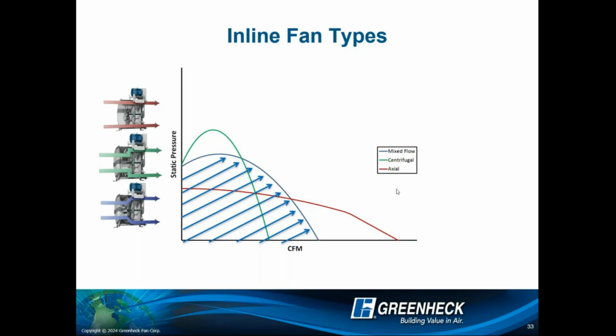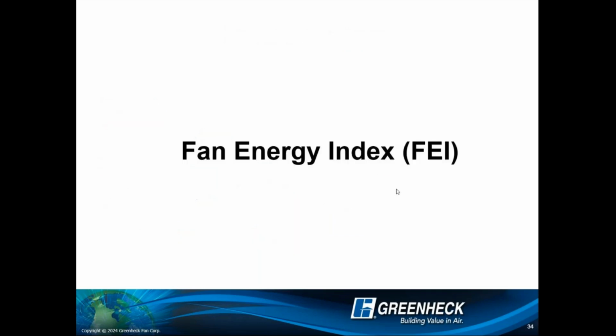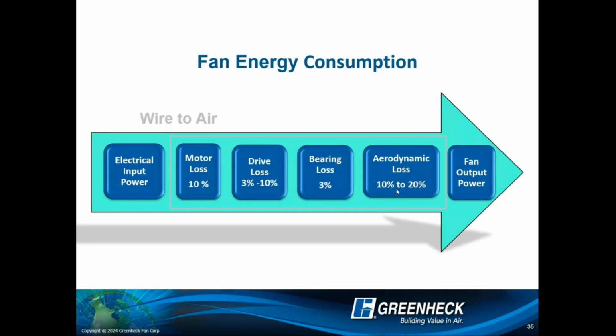And it's a common question I get: okay, I'm looking at this graphic on your screen, how do I know if I've got the right fan selected? Well, I'm glad you asked because our next topic is going to be about fan energy index, right? What is fan energy index? Well, quite simply, it's a look at fan energy consumption that is tied to air, right? I bring in this much power, I move out this much air. It represents everything through the middle.